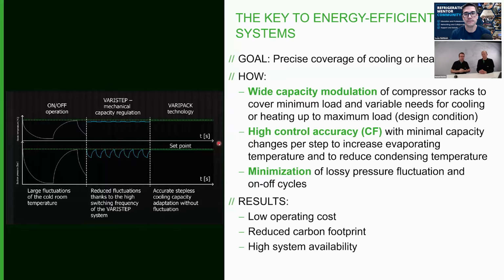And then we talk about the control factor. Later again, I'm going to explain it. The control factor describes the capacity steps between the variable capacity compressor and the fixed speed compressor. This is an important value where we have deeper slides on it.